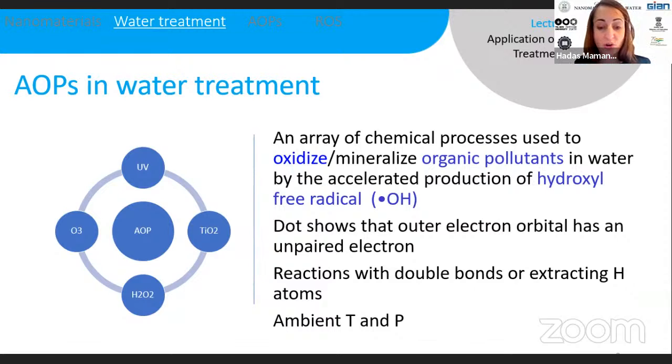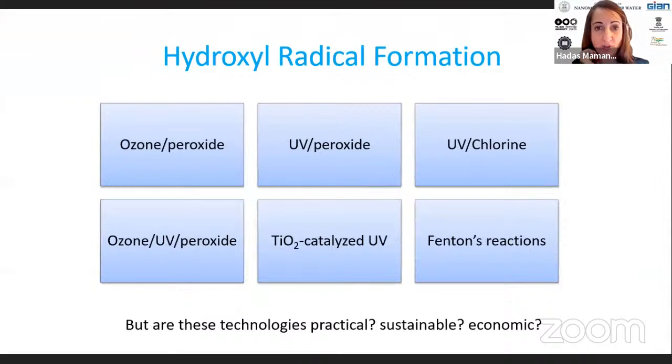Moreover, the second order rate constant of hydroxyl radicals with organic chemicals is in the order of 10 to the 8 to 10 to the 9 liter per mole per second, which is almost a diffusion-based limit. So therefore, the design of the reactor using advanced oxidation processes is very important. Okay, so this is something that is very important to consider. So I think these are the main points to consider.